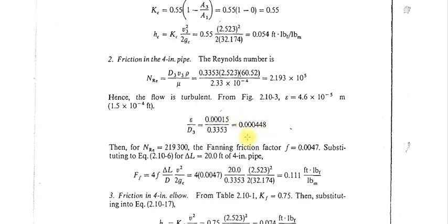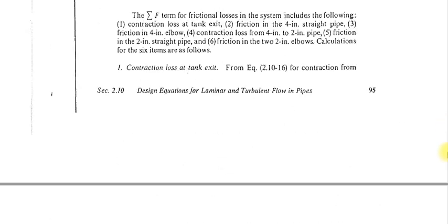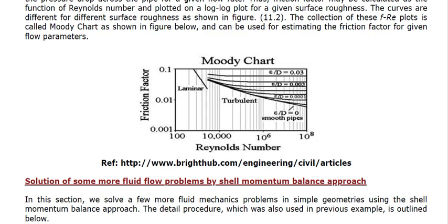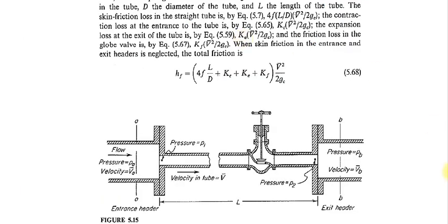This is a dimensionless factor, so you can calculate it in meters or in feet, and the value will be the same. Now you just have to check the Moody's graph. The Reynolds number is known, and the roughness factor is known. Now you just have to use the Moody's graph. So where is the Moody's graph? In the McCabe book, I will show you in the bigger diagram.